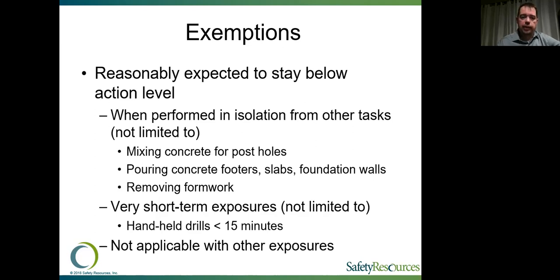Now, when we have things that we can classify as very short-term exposures, like using a handheld drill to drill into concrete, as long as that's performed for less than 15 minutes or so, that exposure would be considered minimal. At that point, the guidelines and the rules would not necessarily need to apply. But also keep in mind that these exemptions are not applicable if employees have other exposures to silica.